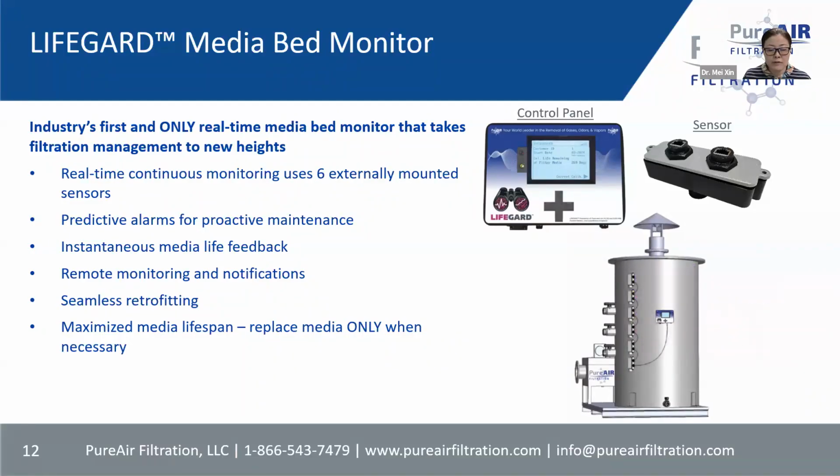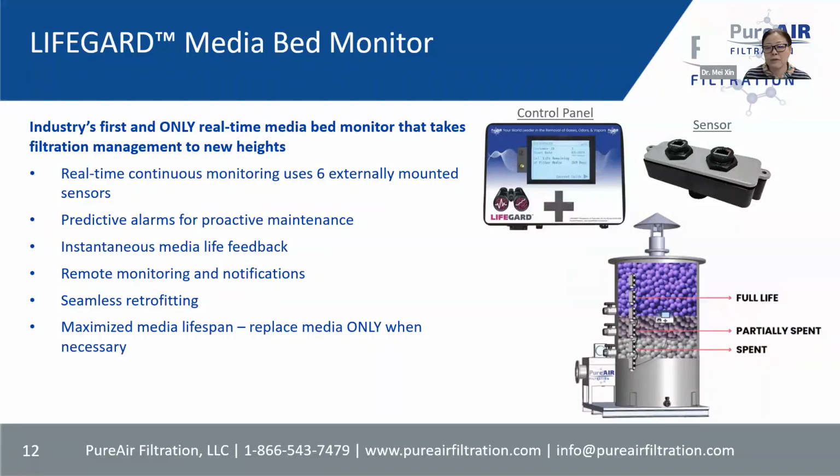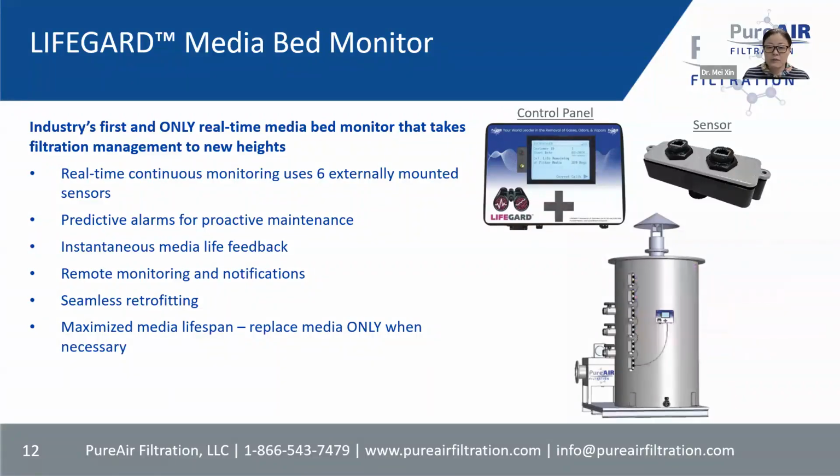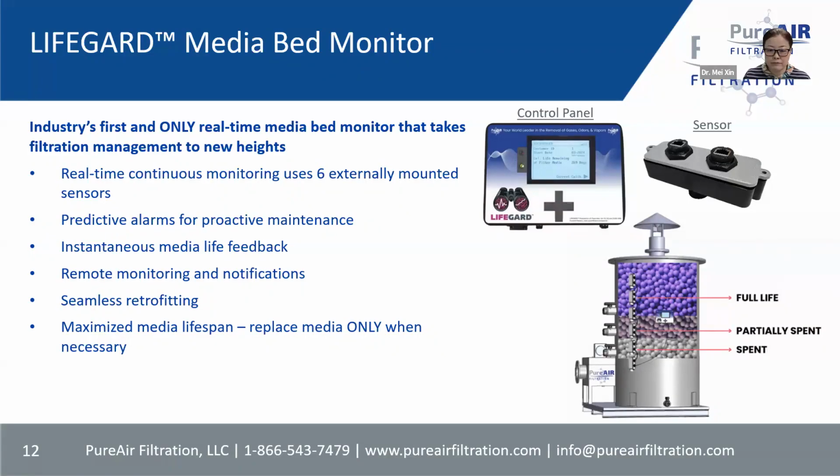That's a more advanced analysis compared to our media life analysis, because there is always going to be a little bit of delay on the media life analysis. So Lifeguard gives you live readings, and it also improves accuracy. It can detect media bed efficiency level changes and calculate remaining media life.